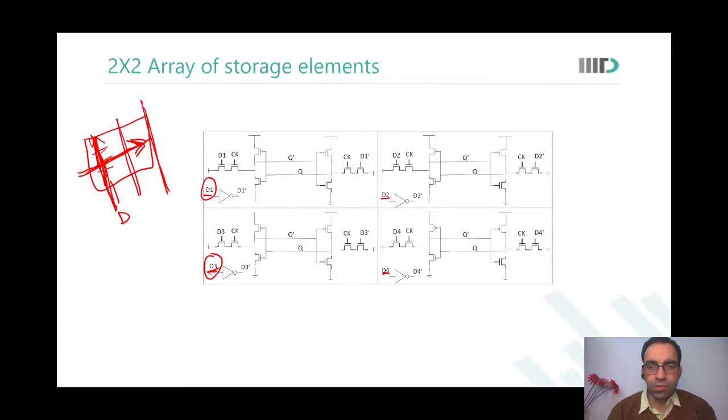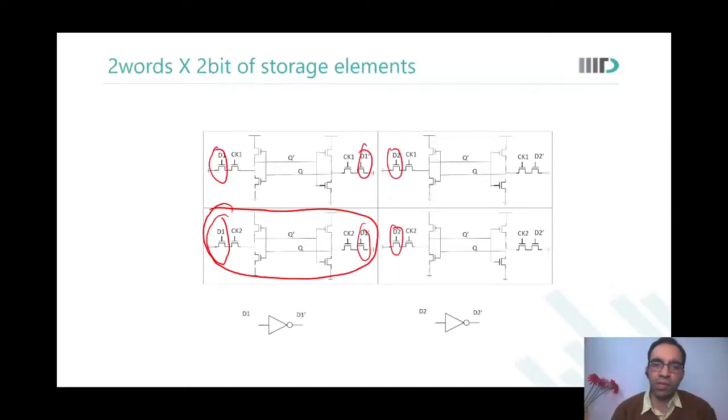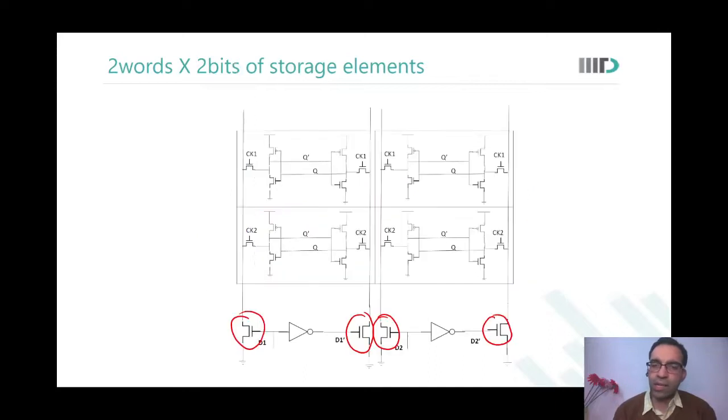Okay. So if it is going to be D1 only, then why put two inverters and put an inverter in every row? Put that inverter down there. So we put this inverter down here. Then we looked at this set of NMOSs. We said, oh, these NMOSs have the same signal. So I shared them also, and I came to this stage. Is this clear?